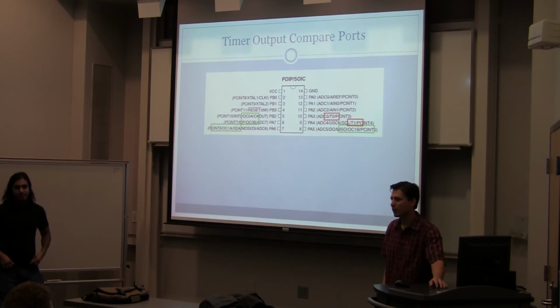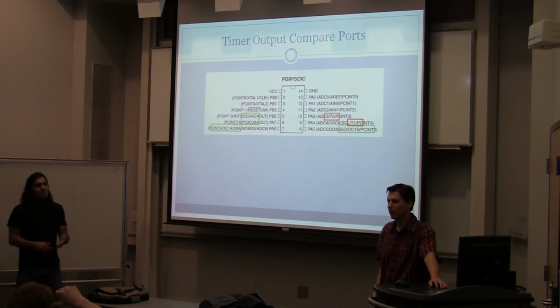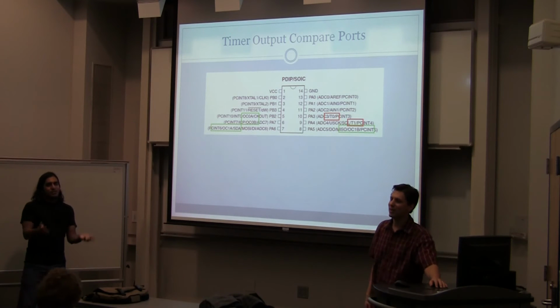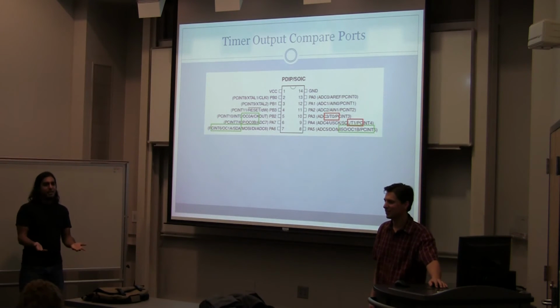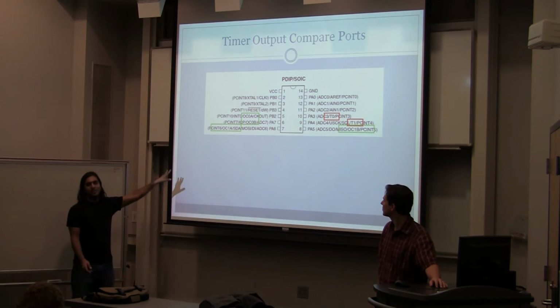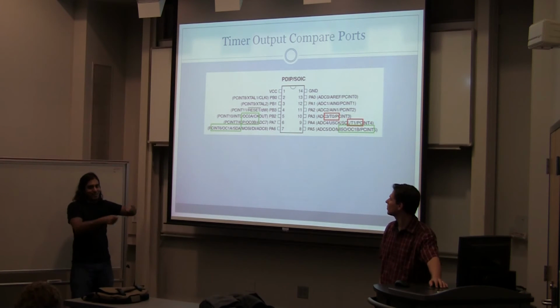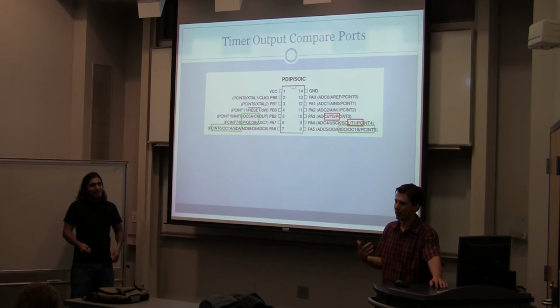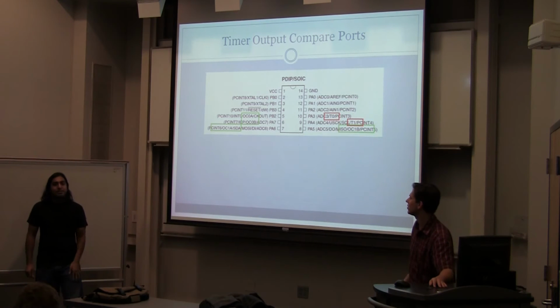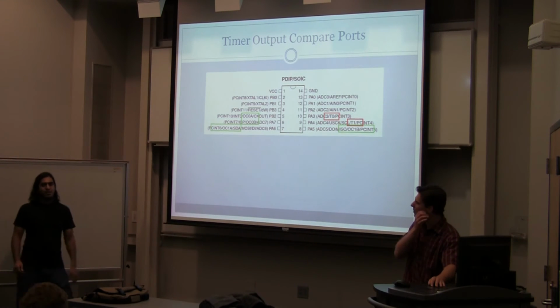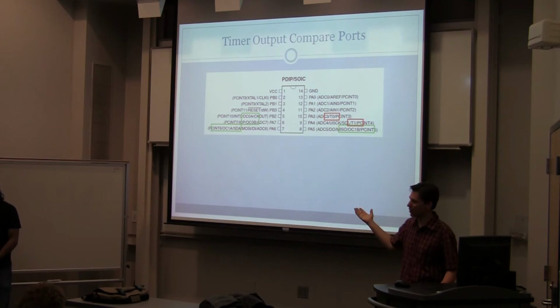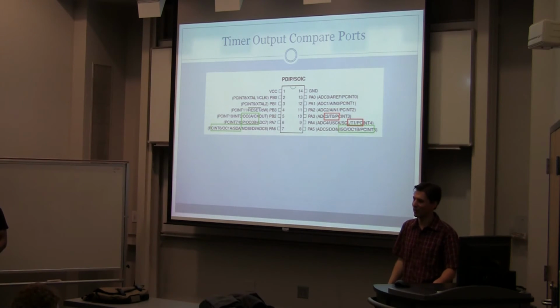Yeah. Well, you can switch which module is active. Yeah, you can do that at runtime, but you have to deal with the circuitry problem of still having the thing physically connected to whatever. I need a multiplexer or something. Yes, you can do that, and that is one solution to this problem. Yeah. Although if you've got a PWM signal, for example, usually that has to be on at all times. Otherwise, you have a maximum 50% duty cycle or something.